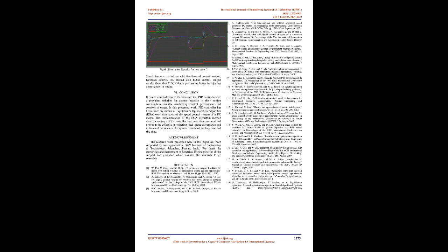Test case 2, considering disturbance torque. For this case, DC motor parameters used are given in Table 1. A unit step signal was given as input to the simulation model given in Figure 2. The simulation was run with ITAE as fitness function. Simulation was carried out with feed-forward control method, feedback control, and PID control tuned with EOA. Output results show that PID tuned with EOA is performing better in rejecting disturbances in torque.